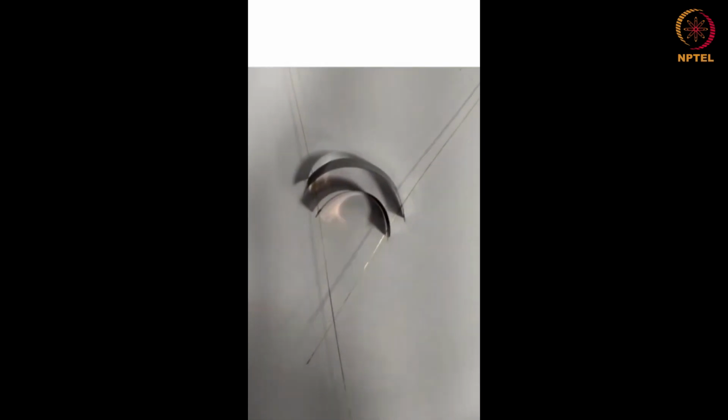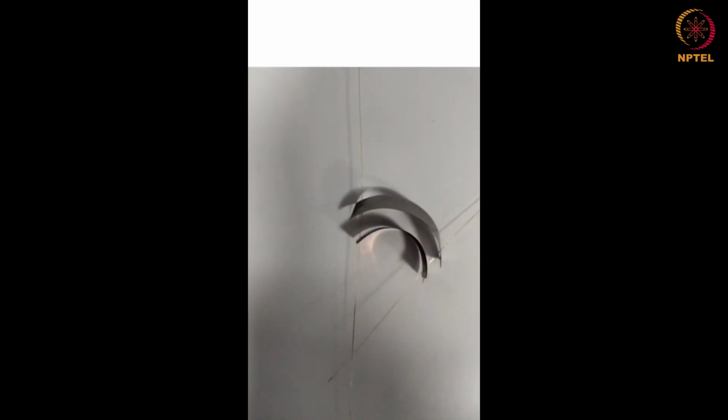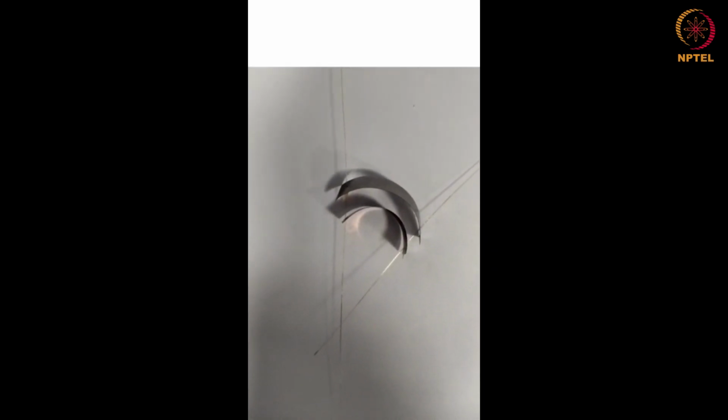This smart actuation of Bimorph has been captured by integrating it with optical fiber using optimal dimensions. Initially, the optical fiber remains in a macrobend state, and upon heating, Bimorph actuation results in bend release, which increases the optical signal, and this bend again gets retained upon cooling.